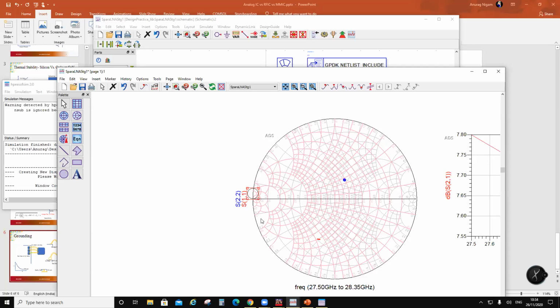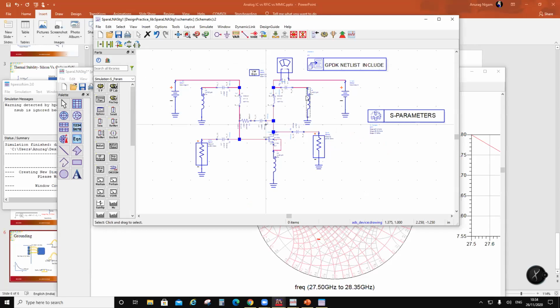Now, if this is not possible through a capacitor, then you better put a stub here. That's why in your MMIC designs, you see a fan here, a radial stub, because that radial stub is giving you a broadband short. Open is transformed to a short. And then you use a λ/4 line to make that short look like an open here. So that's a decoupling. So why do you use that decoupling? Because the capacitors have equivalent series resistance. That's why in MMIC, we will not use a capacitor. We'll use a radial stub and λ/4 line here.